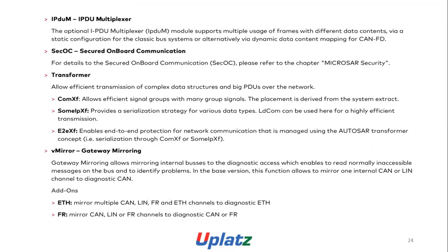I-PDU multiplexer. The optional I-PDU multiplexer module supports multiple usage of frames with different data contents via a static configuration for the classic bus system, or alternatively via dynamic data content mapping for CAN-FD. SecOC, secured onboard communication. For detailed information on secured onboard communication, please refer to the chapter Microsar Security.